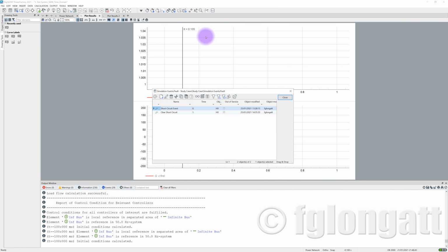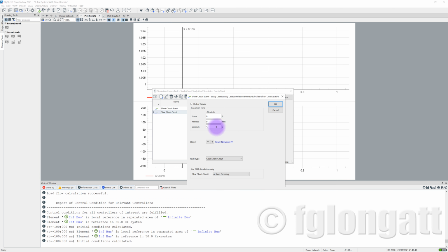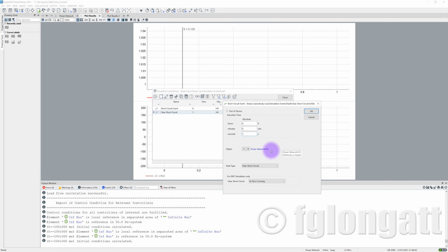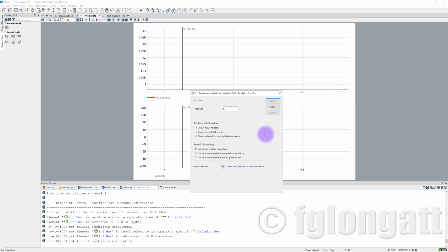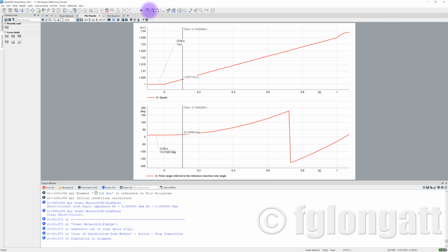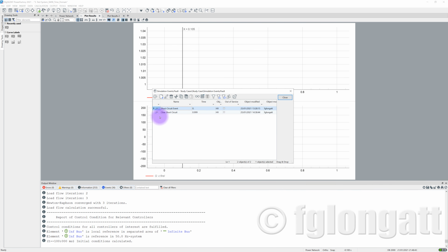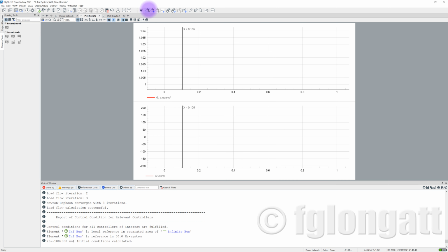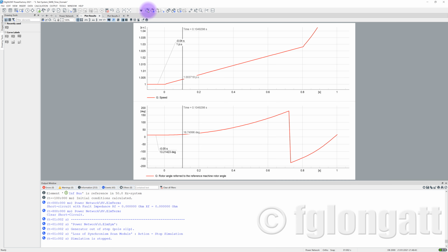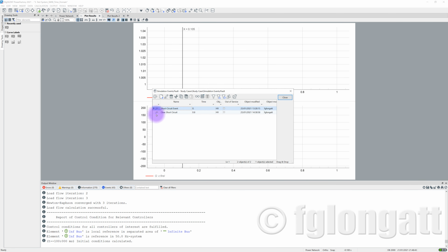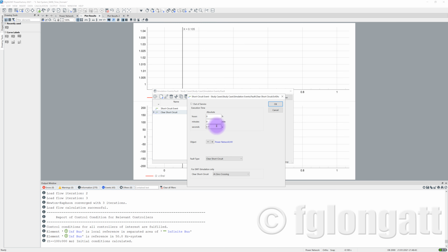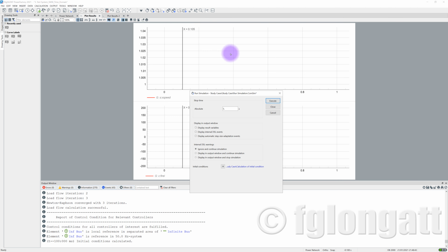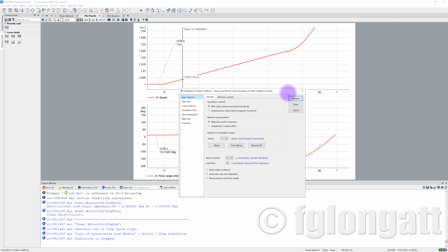I will run initial conditions. Right now, the short circuit is happening and clearing at 1 second, okay? What happens if we clear at 0.99? Okay, let's see. System unstable, okay? What happens if we clear the fault before? Let's say 800 milliseconds. Let's clear the fault at 800 milliseconds. The system is unstable. Okay, let me try again. Let me run and clear the fault at 700 milliseconds. Now I run the simulation, 700 milliseconds, the system is unstable.